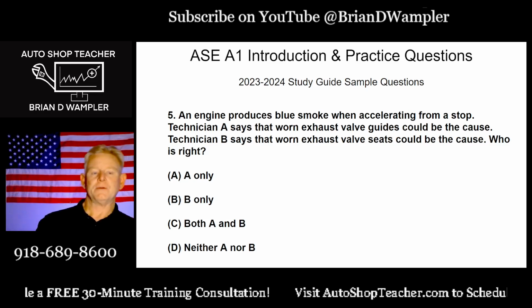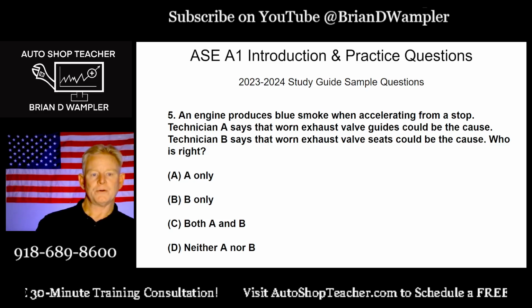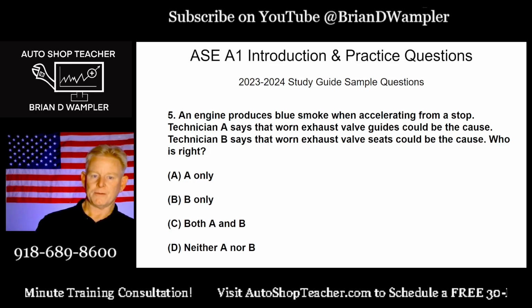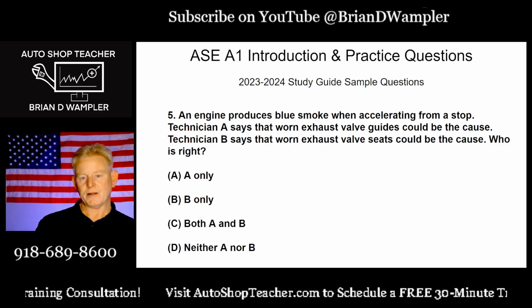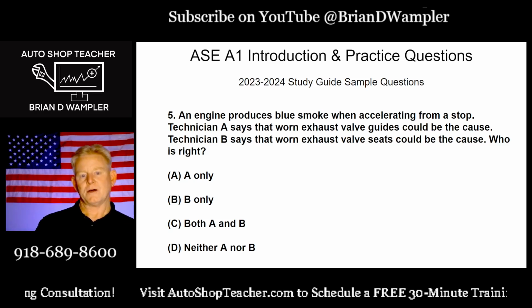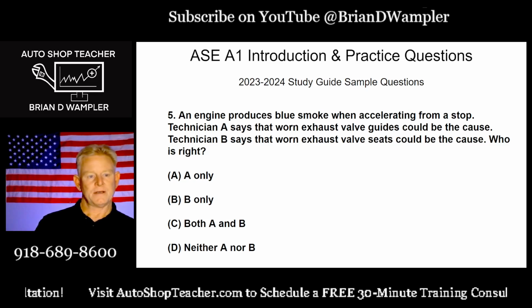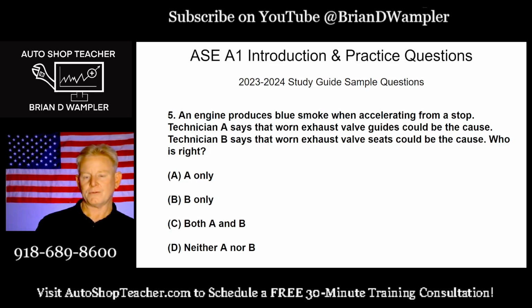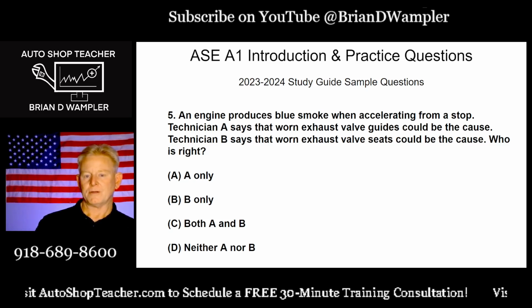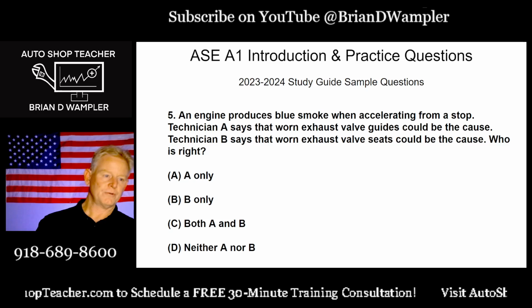So think about the information we have. Engine produces blue smoke when accelerating from a stop. So it's very specific. Blue smoke and accelerating after we've been sitting at a stop sign or light. Tech A says that worn exhaust valve guides could be the cause. Okay, you got your answer on that? Basically, you're trying to agree or disagree.